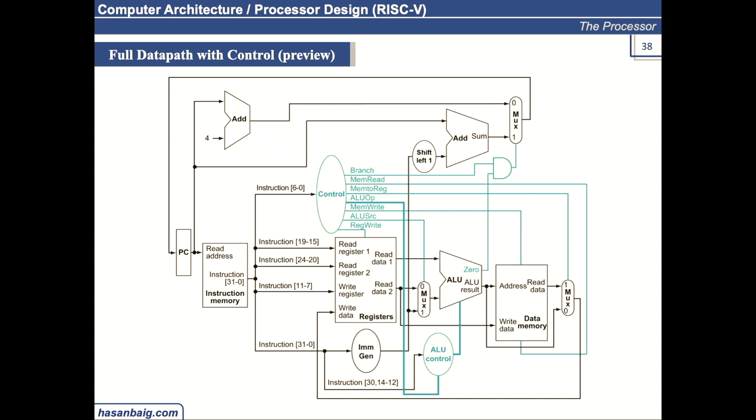Generally, an if-else structure is implemented with multiplexers. More multiplexers means more digital gates, and more gates cause more delay. So it will not be faster if we compare the func3 and func7 fields here.